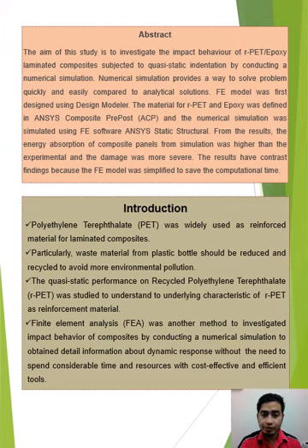Abstract. The aim of this study is to investigate the impact behavior of RPET and epoxy laminated composites subjected to quasi-static indentation by conducting a numerical simulation. Numerical simulation provides a way to solve problems quickly and easily compared to analytical solution. The FE model was first designed using Design Modeler, and the material for the RPET and epoxy was defined in ANSYS Composite Pre-Post SEP. Lastly, the numerical simulation was run using the FE software, ANSYS Static Structural.